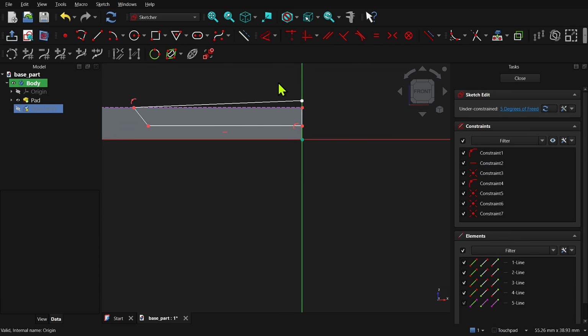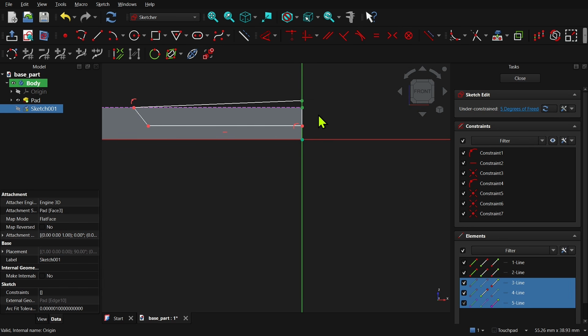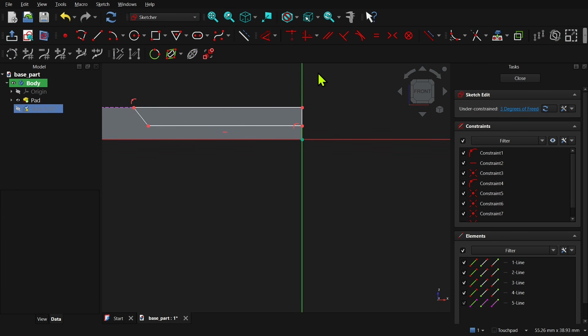Reattach the points by box selecting them. Click and hold the mouse at the top left position and draw a box around by sliding the mouse down to the bottom right. Release the mouse and all within the box are selected, and then use the coincident constraint. The points go red and you're good to continue.